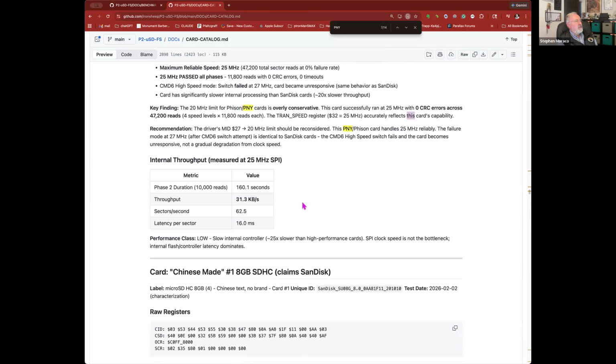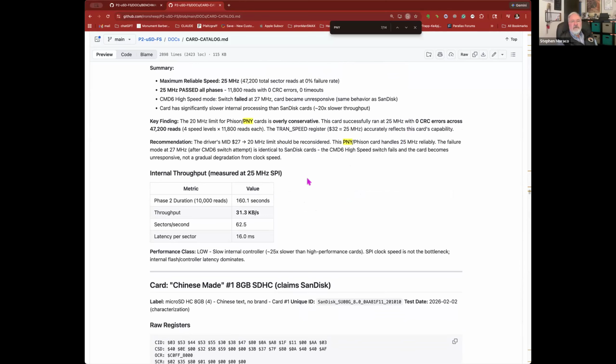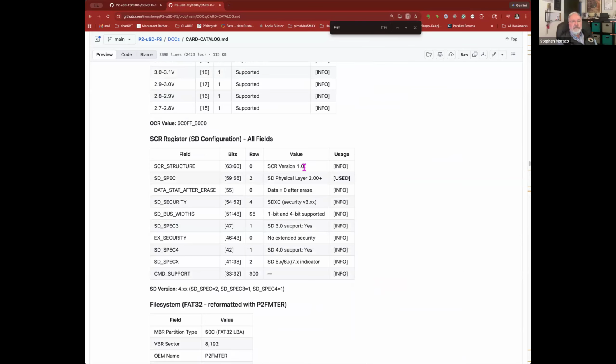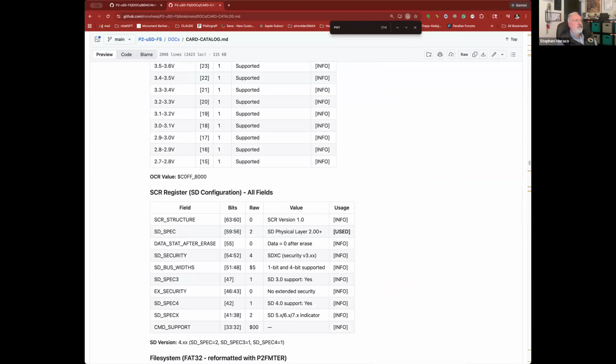So all sector writes are with CRC generation, and readback is with CRC verification, so I know if I'm having any bit dropout to and from the device. And these speeds that I'm measuring on the slides I've shown you are with full CRC support enabled. So high data reliability is the intent.